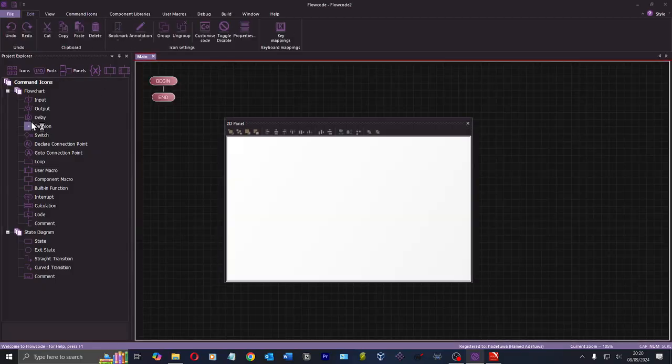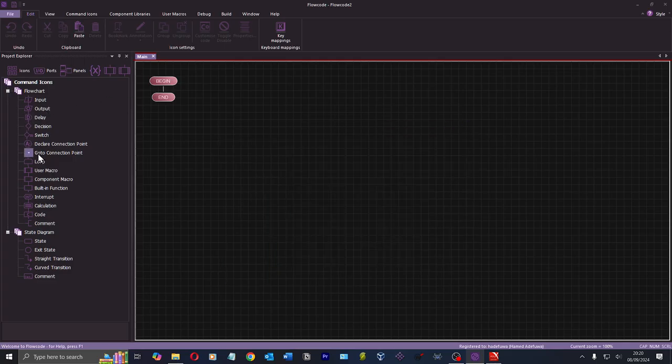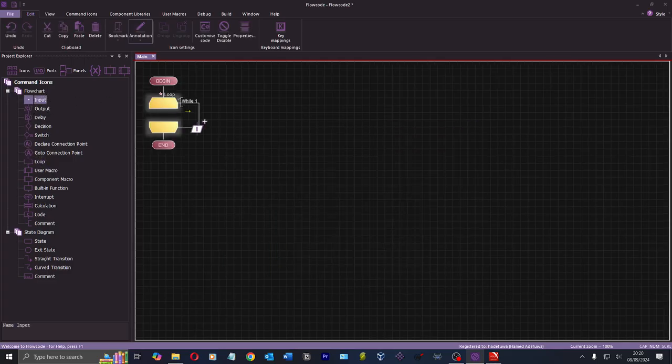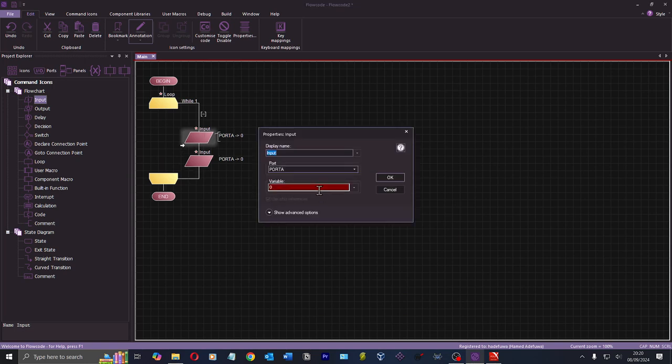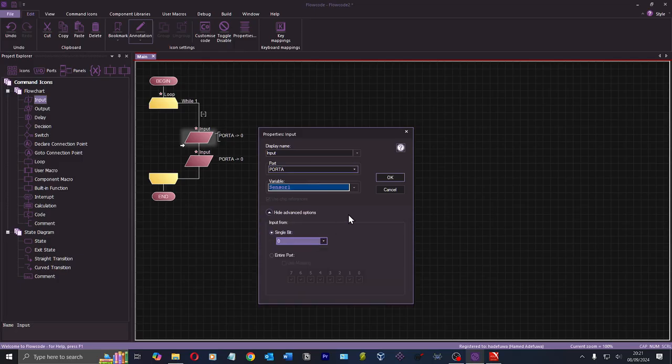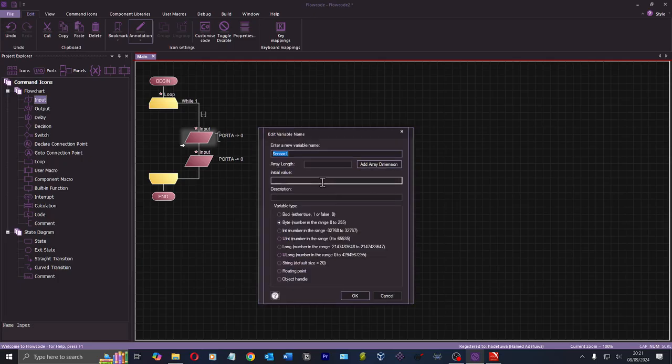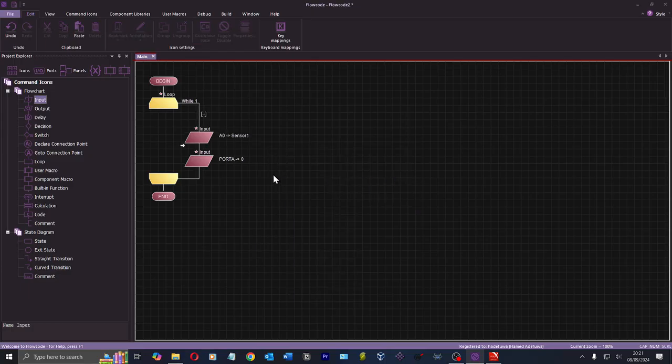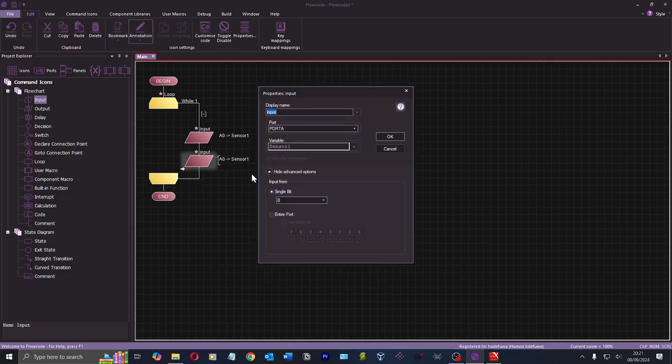we'll define our sensors. So let's do a loop to define our 2 sensors, our switches. So we got sensor 1, and that's going through on 1 single bit, the first bit on port A. Yep, that can be a boolean. Yep, okay. So then same again, but for A1, and that is sensor 2.